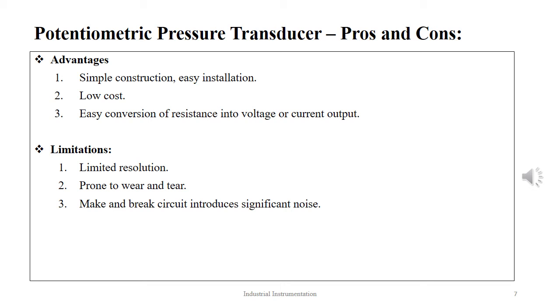The limitations of this transducer are that it has limited and restricted resolution. The device is prone to damage due to wear and tear. The make and break circuit causes significant noise in this circuit.